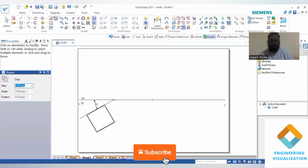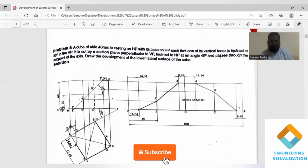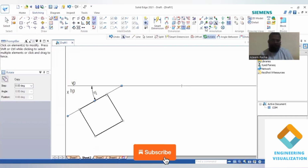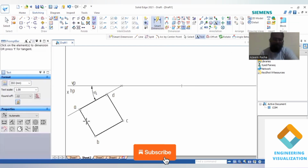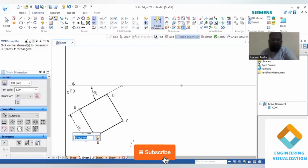Now after this, we can draw the front view of it. The front view also has a 40 mm dimension because it is a prism. So we can write the naming for it, A, B, C, D. Only top face notations we can write; we're not writing all the faces here. We can show the dimension here. It is 40 mm.